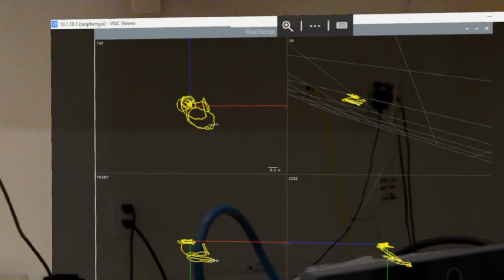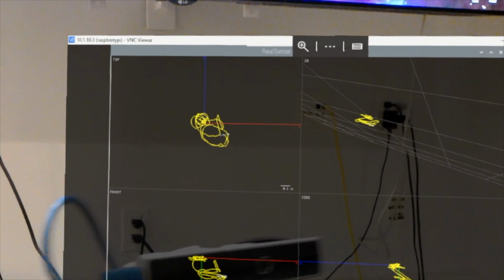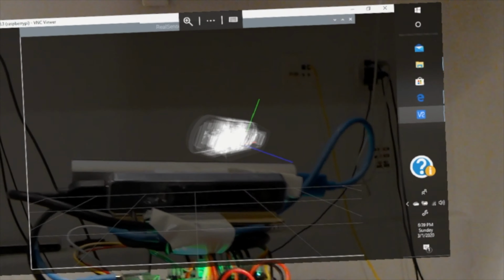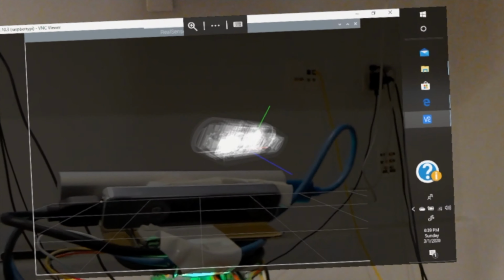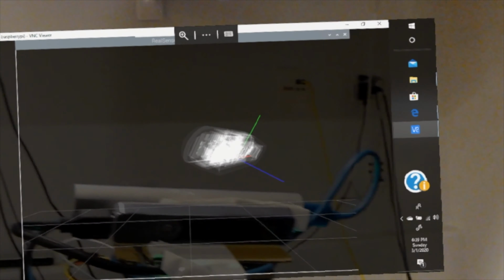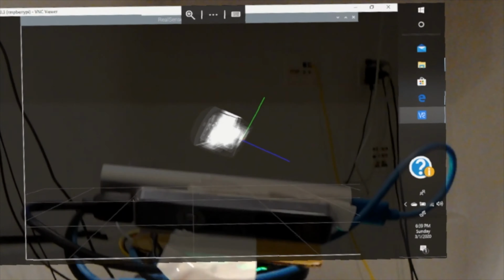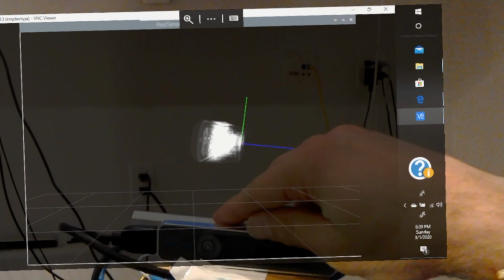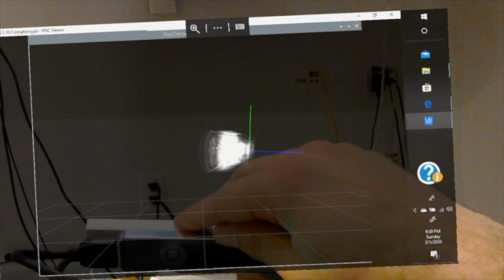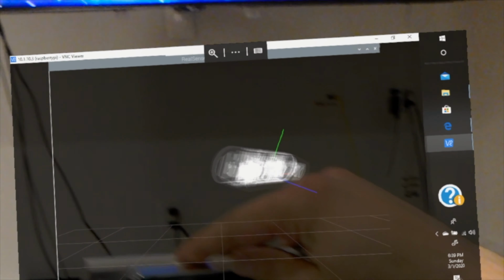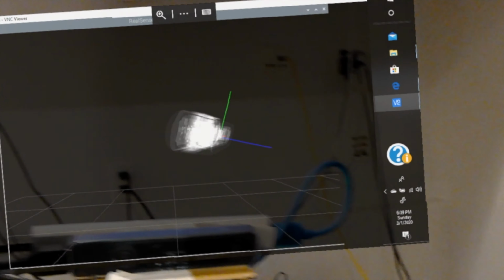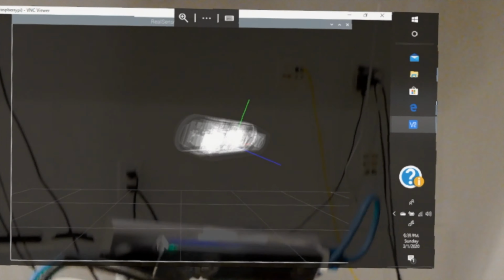And that's what we want to do. We want to uplift these type of systems, versus some of the more unbelievably expensive. You need like a 6 or 9 axis inertial measurement unit to get the yaw, pitch, and roll from the robot. But you can use this information and feed it back into the control, perception engine to actually send signals to the motor, send signals to the servo, and then feed it back into the sensor system. So we can go along each one of these axes. And the T265 also provides linear velocity, angular momentum, and this information is very useful as long as you know how to use it and where to apply it.